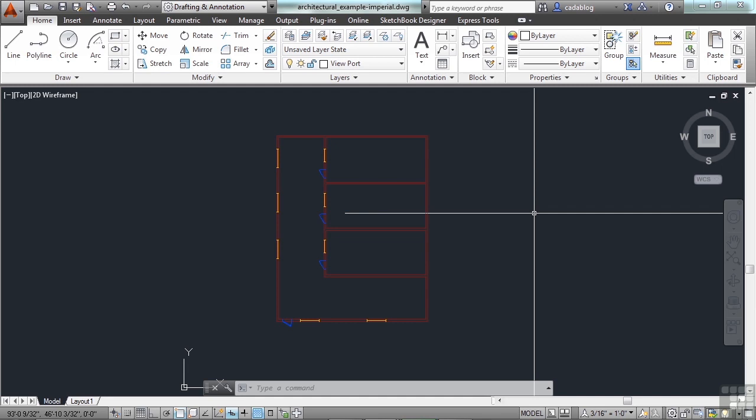Well, that bit of information that I just gave you just discusses how AutoCAD handles frozen or off layers. It used to be a real big deal back when we worked in AutoCAD in DOS, and your processor just took a long time to generate on your screen all of these lines that you had. You would turn things off or just freeze them instead because it just handled it differently. It didn't process them even though they weren't there. Well, that's not as much of a case now. Our big processors with our tons of RAM in them can handle these things.